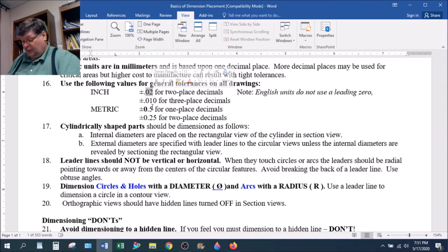And that's how you determine the tolerance for any of your parts for your final project. Take an average of about 5 dimensions on the same part. Throw out the largest dimension and the smallest dimension, because you might have made a mistake. Average the remaining ones, and that will tell you not only how big the part is, take the median dimension, but it also will tell you what your tolerance is, so you can write that in there.